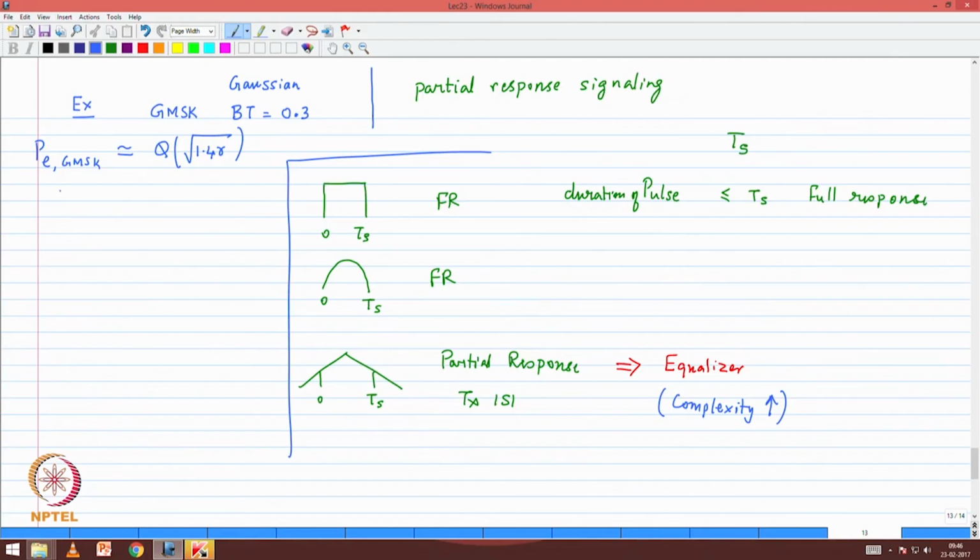The way to look at it is, if I were to specify a given BER level, that corresponds to some SNR. So basically from the Q function you can find out that 2 times gamma BPSK, which is what will give you that BER, will map to 1.4 times gamma GMSK, because the arguments of the Q functions map to the same BER value. So for a given BER, if I want to satisfy it with both BPSK and GMSK, I must satisfy this condition.